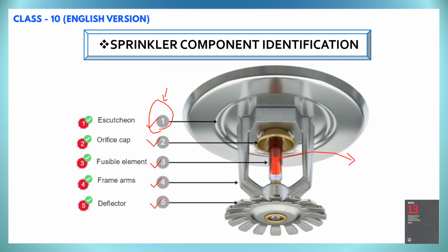So to summarize, sprinklers consist of a threaded frame, as you can see at point number 4, with a specific waterway or orifice size, which is point number 2, and a deflector for distributing water in a specified pattern, point number 5. So a closed or sealed sprinkler refers to a complete assembly including the thermosensitive operating element.